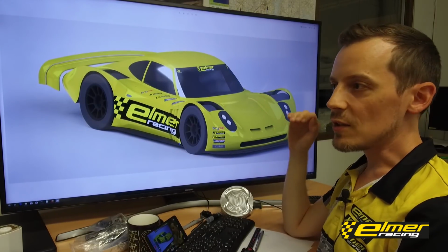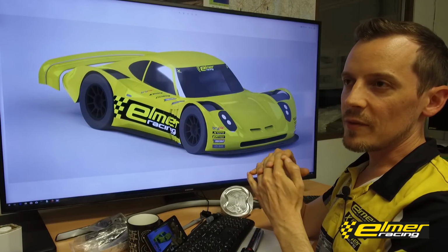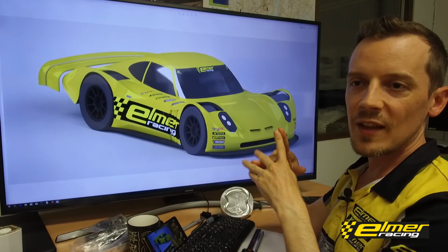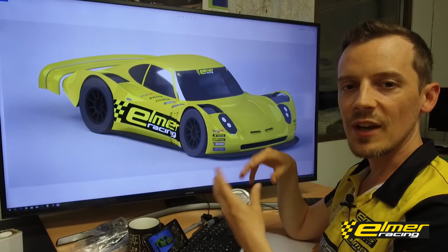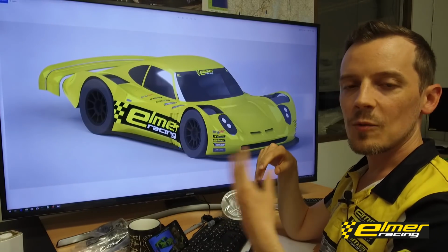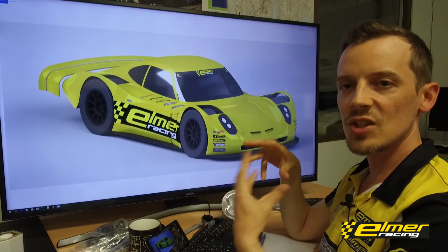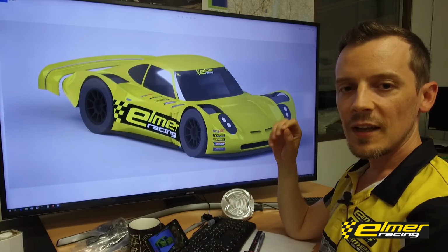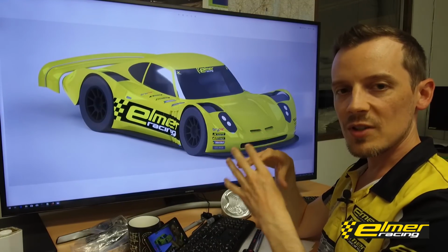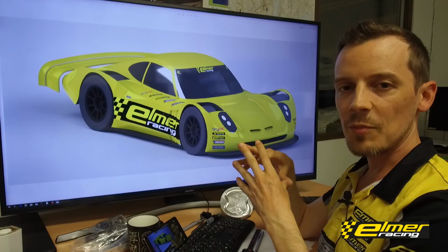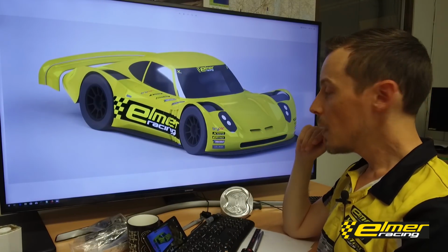Having the brake components and the uprights or hubs designed with the same company is also very important, so that we can get the whole package designed as well as possible and get the suspension mounting point loads transferred as close as possible to the brake caliper mounting points, and all these kinds of design aspects.